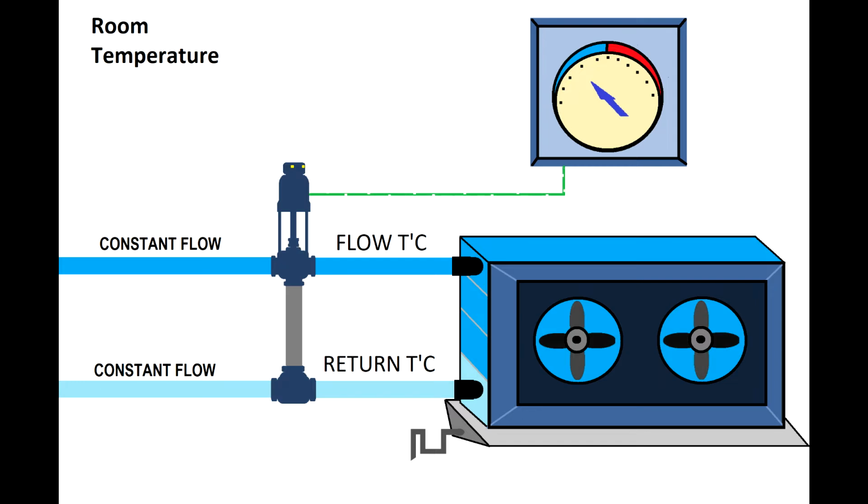There's another problem, though. If the cooling agent is not cold enough, the heat exchanger will not run below the dew point, and then the air that passes by will not allow the moisture to condense onto the heat exchanger. As you'll see here, onto this drip tray there's no condensed water, so the air will keep its humidity, and people will sweat on the premises, because even if you cool the air a little bit, the moisture will be pretty high, and then people will feel pretty uncomfortable.